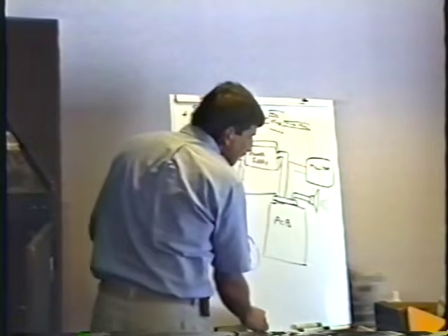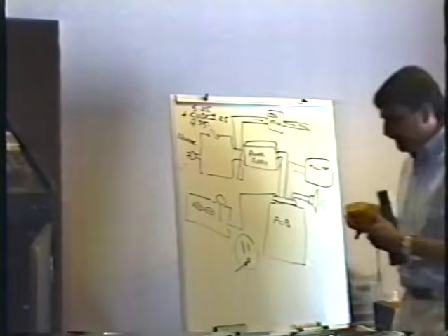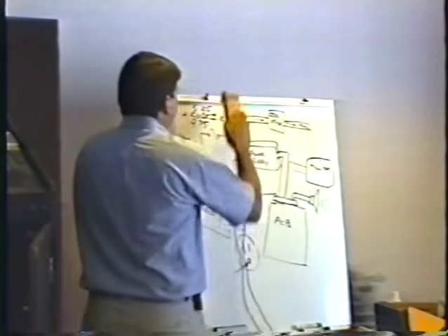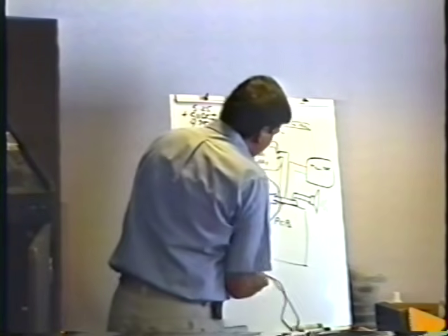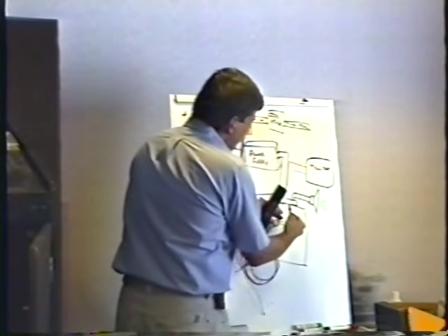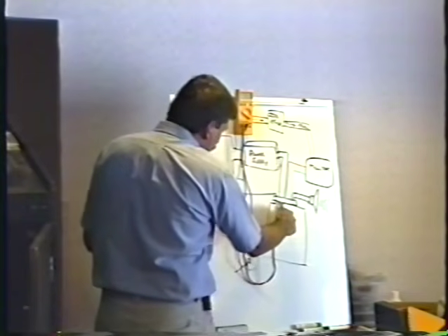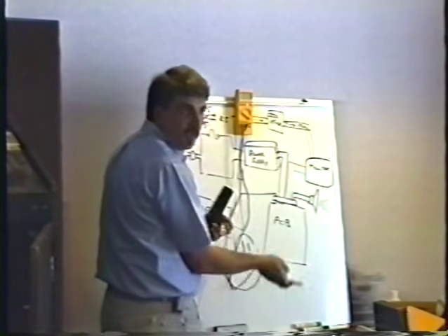When I want to measure the 5 volt power supply, I measure it here at this connector. With the power turned on and the meter set on DC volts, I put one meter lead on ground and the other meter lead on plus 5, and with my meter connected to the board, adjust the voltage on the power supply.